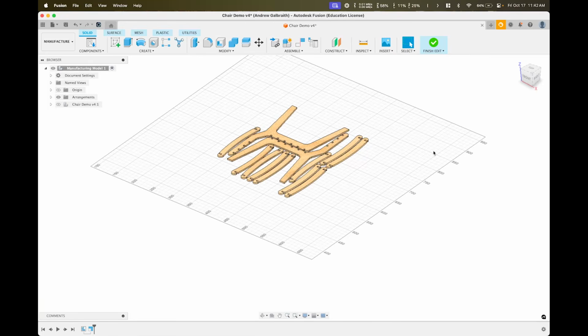The reason we did it in here is when you go back to your actual 3D model, that'll still be in full scale. Like I said, you can do it in your 3D model. If you've already done it in your 3D model, you don't need to scale right now. But for this manufacturing model, that's where I'm going to scale it. Cool? I did 0.25, so that's a quarter scale. Because we have a 4 foot by 4 foot for our final project, but right now we're doing 1 foot by 1 foot on the laser cutter.